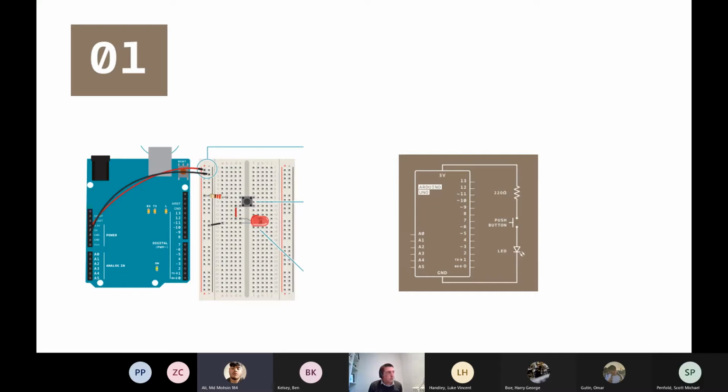When clicked, it will light up. Exactly, great. So when you push the push button, which is this black circle with 4 pins attached to it in the diagram on the left-hand side, that means the loop is completed, and so current can flow through the loop shown on the right-hand side here, and crucially current will flow through the LED, and that will mean that the LED lights up. So that's how that circuit works.